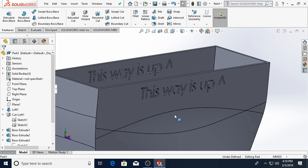In that case, you wouldn't be able to create a sketch on that rounded edge because you can only create sketches on two-dimensional surfaces. So what you would have to do is create a reference plane that was tangent to this curved surface, and then create the sketch on that reference plane, and then click this wrap button, which would project that plane around a curved surface. And then you could create the extrusion or the cut as you see fit.